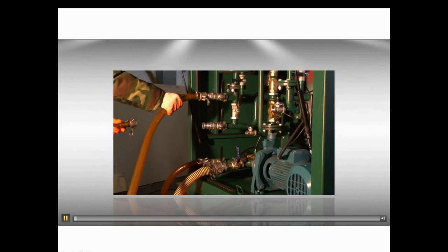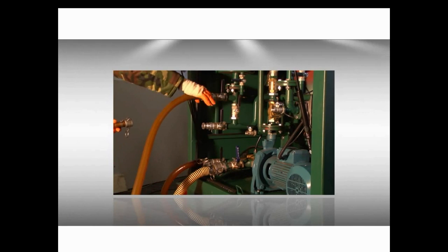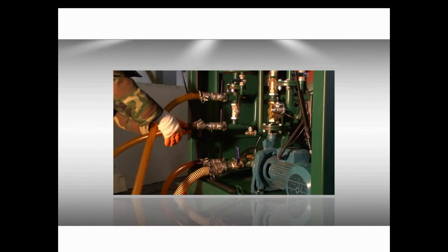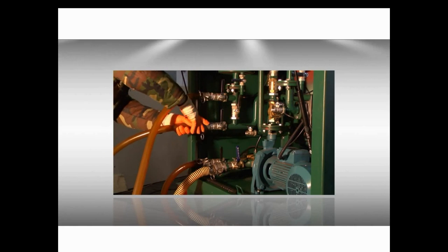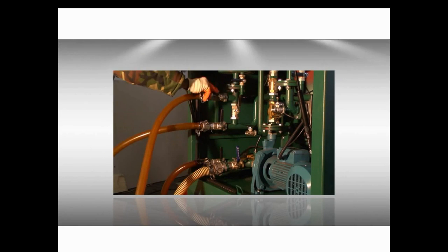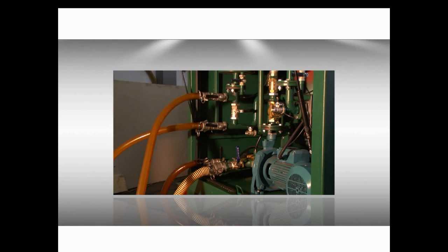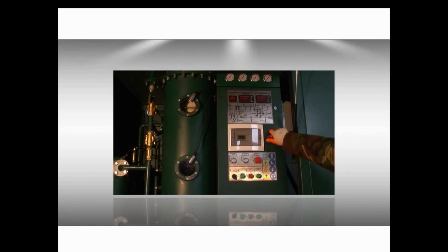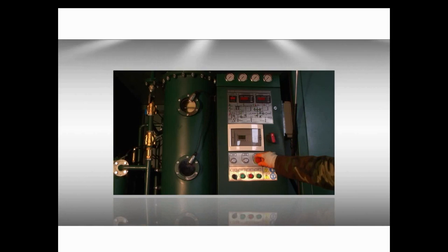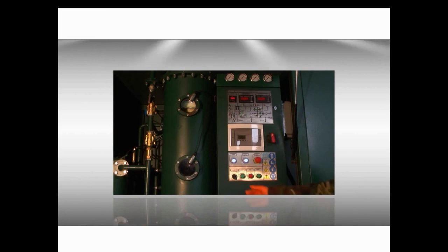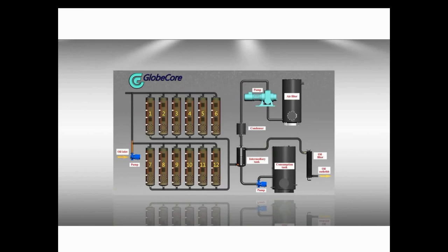Acidity is reduced to 0.03. This difference seems to be negligible, but because Fuller's Earth has limited absorption, we will treat only a quarter of the transformer, 5,000 liters. And 5,000 liters with 0.03 acidity mixed with 15,000 liters, which are still 0.1 acidity.